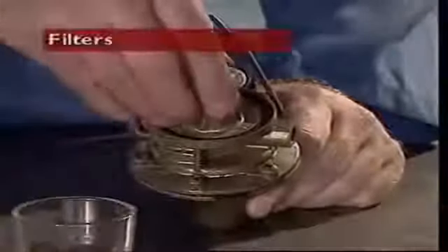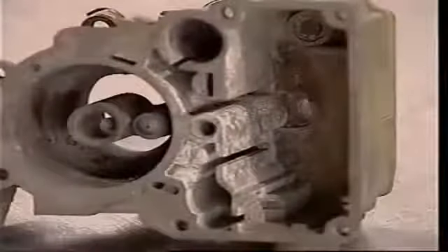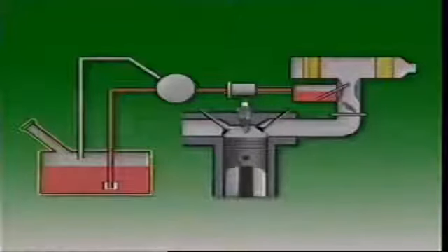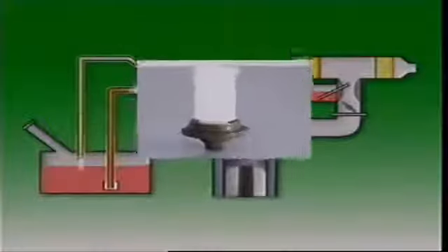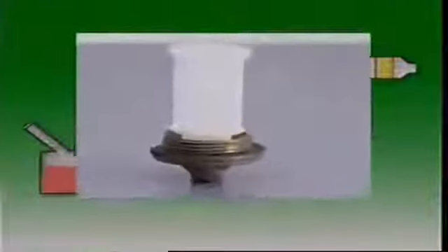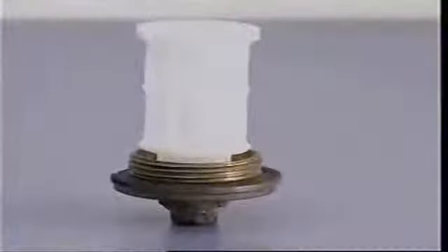This section examines filters for carbureted engines. Fuel must be kept clean, or the jets in the carburetor could be blocked or corrosion can occur. So fuel systems always contain filters. In this carbureted system, a fine filter of nylon or gauze is fitted to the pickup pipe in this petrol tank. A large surface area is provided to allow adequate flow rate and better filtering.